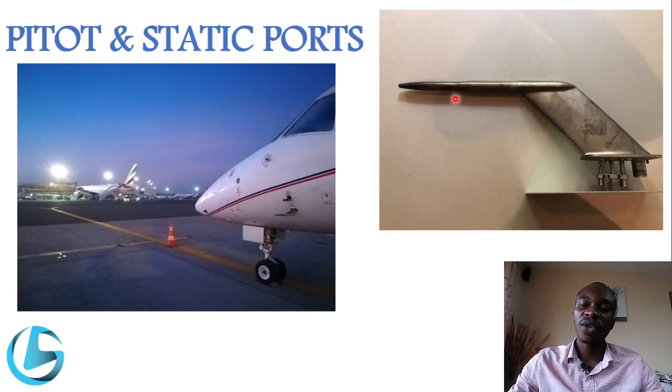In some aircraft configurations, you have a separate pitot tube and static ports on different surfaces, but on most aircraft they are combined on the pitot tube. Like this one here, it's a combined configuration where you have a ram port for the pitot pressure and the static ports for the static pressure.